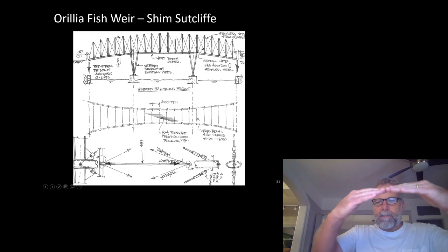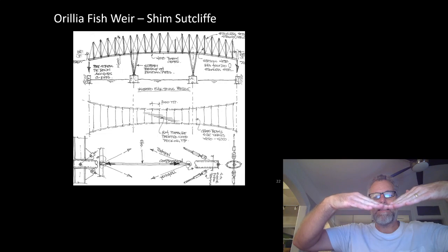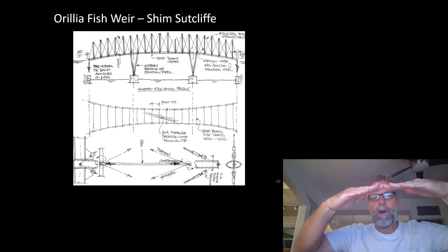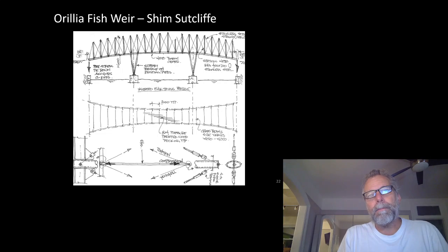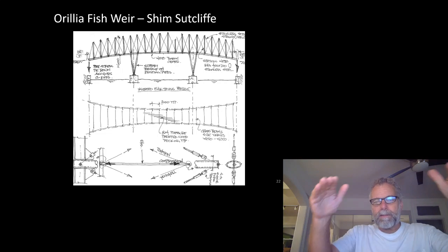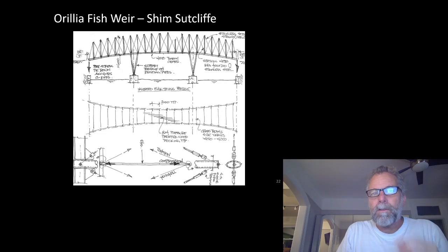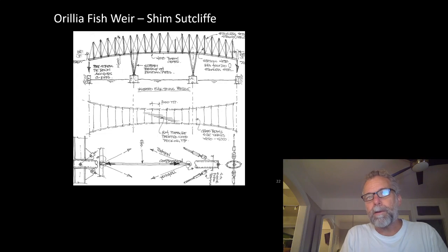What that means is that where a typical beam sags this way, over a support it sags the other way. So in the span the bottom is in tension, but over the support the top is in tension. So if we're going to do a Fink truss, we would naturally invert the Fink truss over top of the supports.